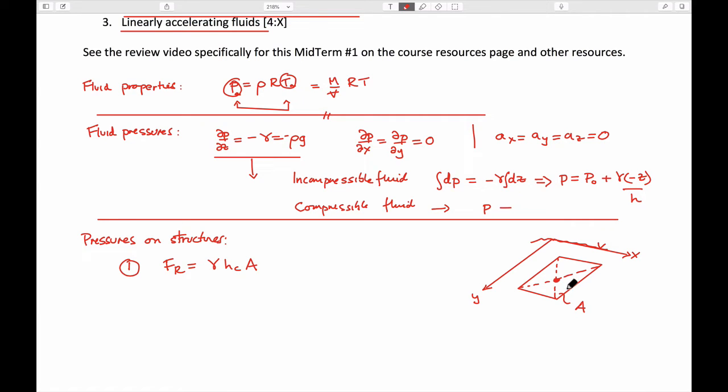And I guess we can draw the important geometry of this, that this is the y-coordinate of the centroid. And when we want to calculate the pressure, the force that's acting at the centroid, we merely calculate the height of that centroid below the surface, which we'll call h sub c.